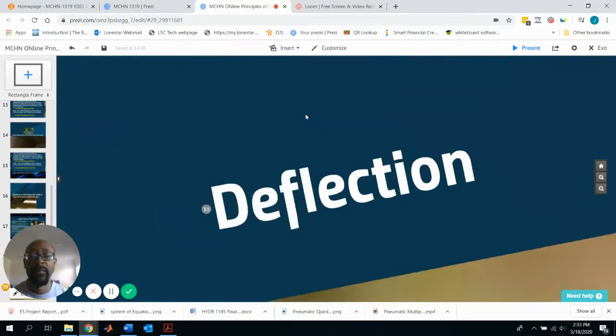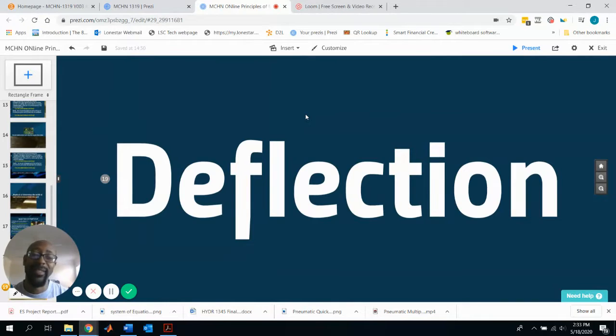One of those problems is deflection. And to mention this, in particular with the milling process. Since you're milling and you have your cutting tool coming straight down, but it's going at the side, pushing at the side a lot. It's cutting at the side. And so there can be some deflection that happens there. And of course, because of that, that limits the precision of the milling process.